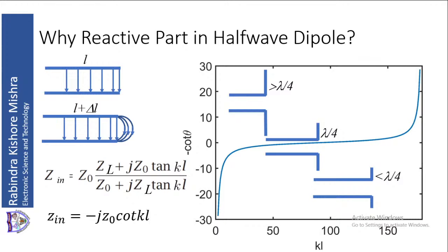will not go out. The field just outside the two wires, the upper wire and lower wire, you see the figure here, the top left figure, the upper wire and lower wire, the fields are in opposite phase. Therefore, in the far field or at a distance, they will add up in opposite phase, which means they will cancel each other. So there will be no field away from the two-wire transmission line. So theoretically this should happen, but practically there is a separation, so there will be some amount of negligible field.